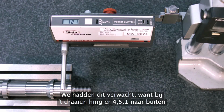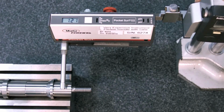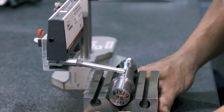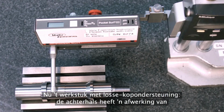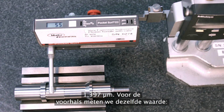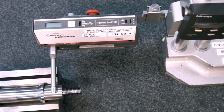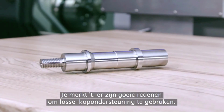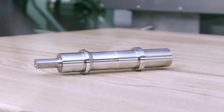This should be expected since this feature is cut hanging out at a 4.5:1 length-to-diameter ratio. Moving on to the tailstock supported part, the rear journal has a finish of 55 micro-inches, and moving forward to the front journal, we find an equal value of 55 micro-inches. It's easy to see there are great reasons for using tailstock support.